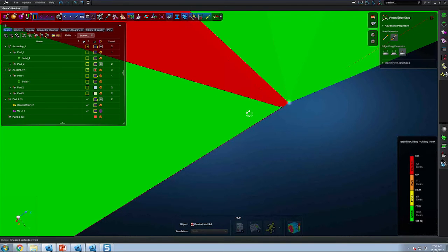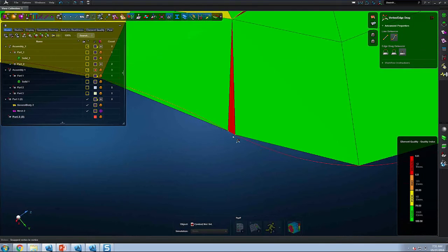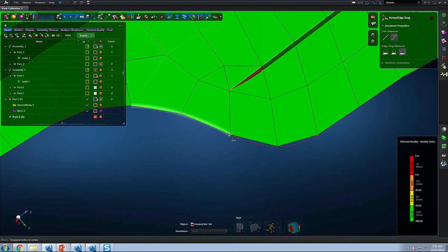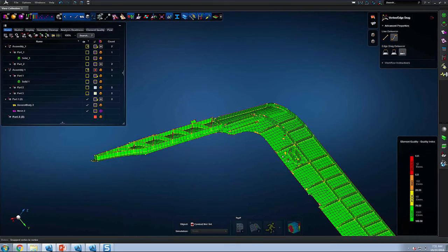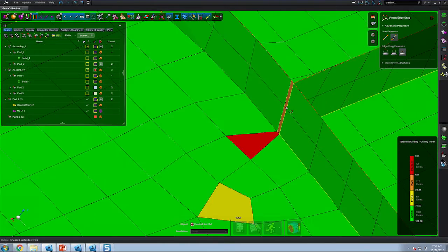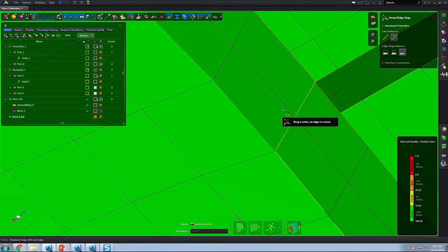As you saw here, I'm using a mixture of quad elements and tri elements. You can also specify to use just tri elements. I know here in the registration list, some of you may be doing injection molding simulation where your need is to use very fine tri meshes. You can also specify that in the application.